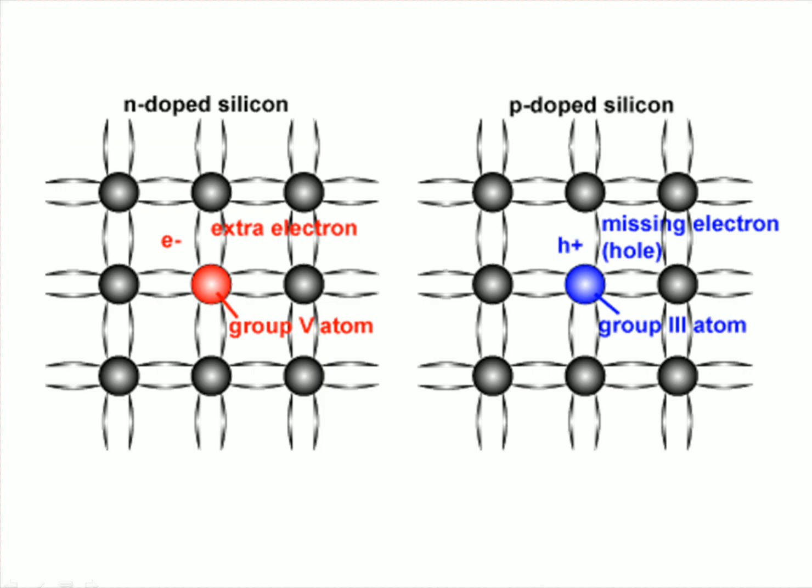There are two types of semiconductors. One is p-doped, another is n-doped. That's why we say p-type and n-type semiconductors. For the p-type we create a positive hole, so we decrease one of the electrons from the structure, and in the n-type we add an extra electron. That's what conducts. For the p-type, we create a positive hole, so the next electron would move to that one. And for the n-type you have an extra one, so that extra one would move around, like in metals.